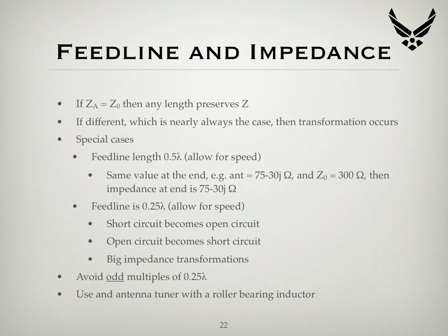for M.A.R.S frequencies that are outside the normal range that are used in amateur circles, you need to have an ability to tune over a much wider range, and you'll find that a roller bearing inductor, which can be continuously changed to the actual contact point, will give you much more flexibility in terms of being able to tune your antenna to operate on particular M.A.R.S frequencies.